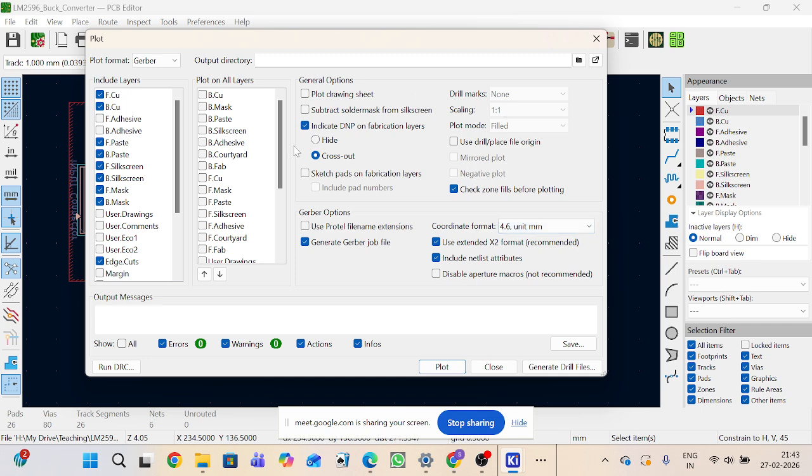Solder mask, ma'am, what? Solder mask is on which we solder components. This masking is like, if you see, there are different colors on your PCB, like black, green, red. That is the masking of that particular PCB. Silkscreen is what? Outline and text for identification purposes of components. So this is a silkscreen.